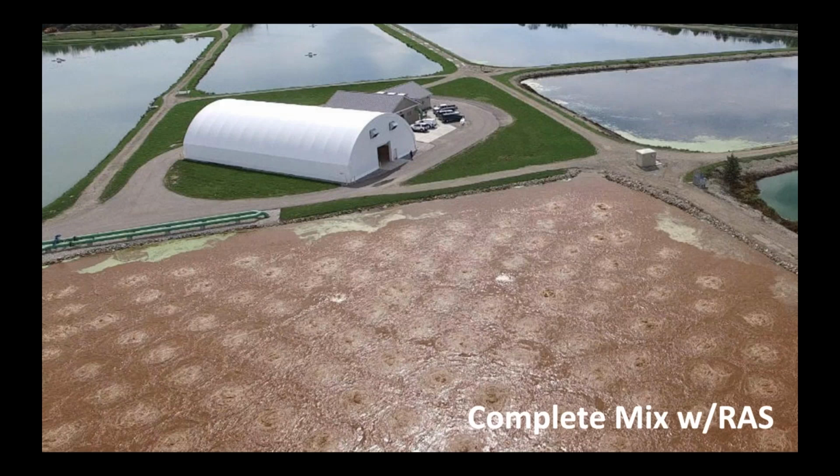One of the main benefits of this is that the lagoon has such a big volume, and the retention time, even though it's pretty short within a complete mix lagoon like this, is still way longer than a typical aeration basin. And so you can handle a lot of I&I, you can handle a lot of extra flow, and the lagoon itself just equalizes that flow. In this particular example, they have a dairy that flows into this plant. It's an industrial dairy that flows into the municipal system that gets treated at this plant.